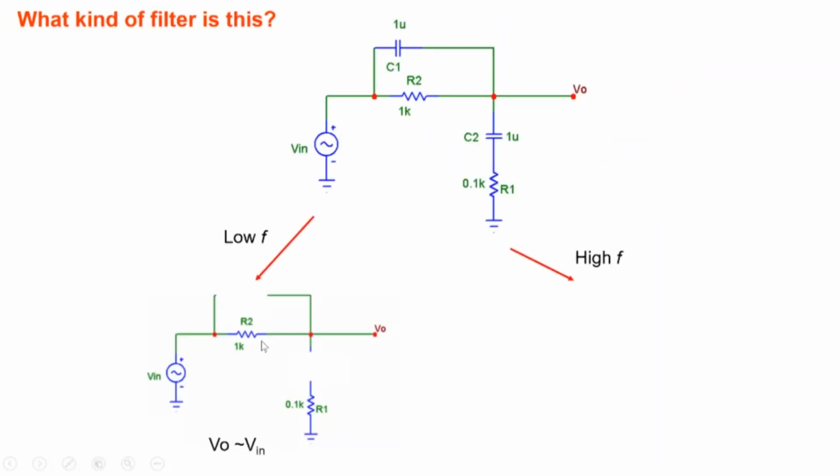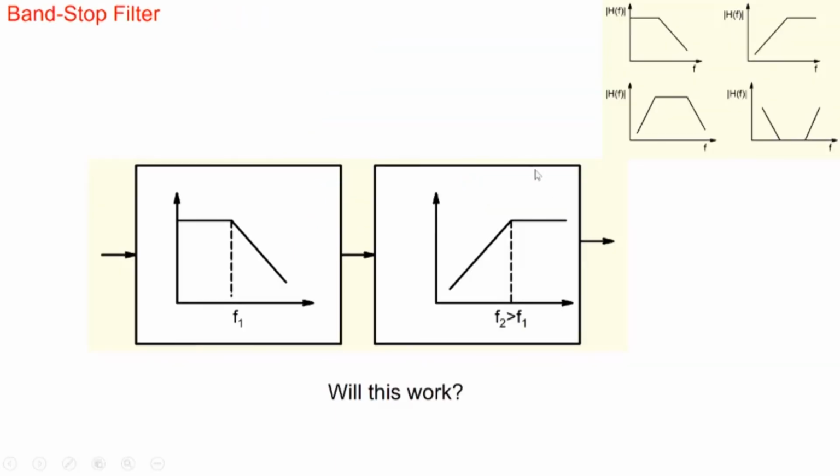That's why, when we have drawn here, if we go back, this would be an ideal filter if it were constant, and at this particular point it abruptly drops to 0 or a very, very high value here, right? So this is not so gradual, but it attenuates or rejects all the unwanted frequencies and perfectly passes all the wanted frequencies, right? So that would be an ideal low pass filter, a rectangular shape like this. An ideal high pass filter would be constant here and then abruptly drop here, right? The more gradual the attenuation, the less useful the filter is in attenuating the unwanted frequencies, right?